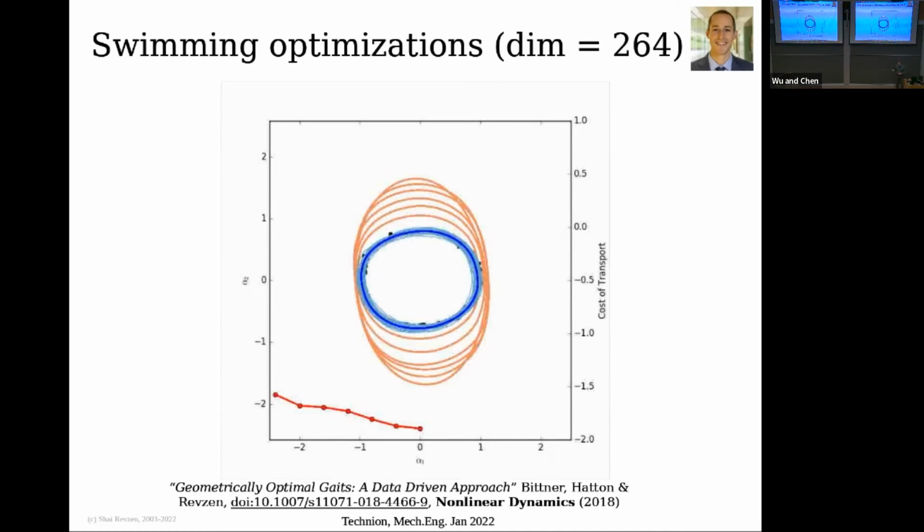If you ask yourself, for a slipping velocity, so for a non-zero velocity, if you're going to perturb that velocity around, how much will the force change? So what's the perturbation model of Coulomb friction? It turns out that that perturbation model is very linear. That is, its first order approximation happens to be very, very good. And I think this is why this is working.